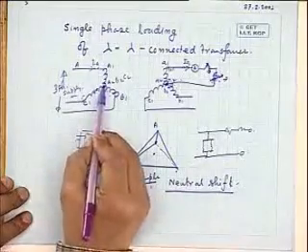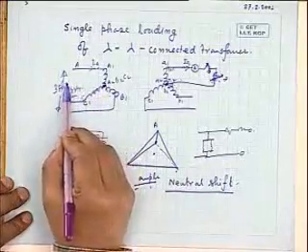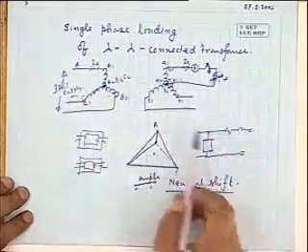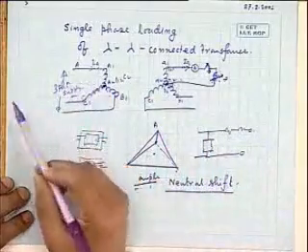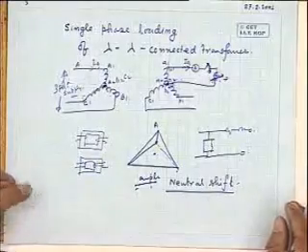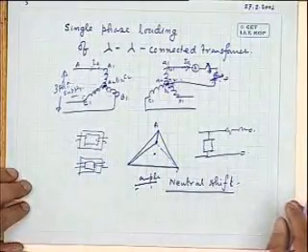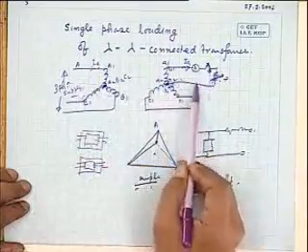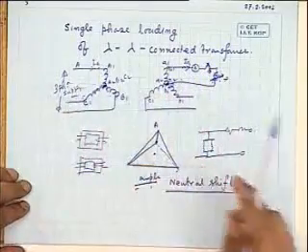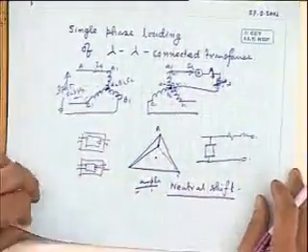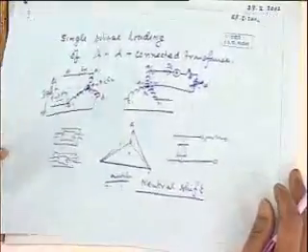And then you can solve this, of course, by connecting this neutral point. If you connect to the supply neutral, these problems will be solved. But in that case, this neutral wire will carry that third harmonic current and may interfere with the communication network. And once this happens, of course, that loading problem will not be there if you connect this neutral. So this way it can be done. And lastly, I will tell you these problems, of course, will not be there in a zigzag connected transformer.